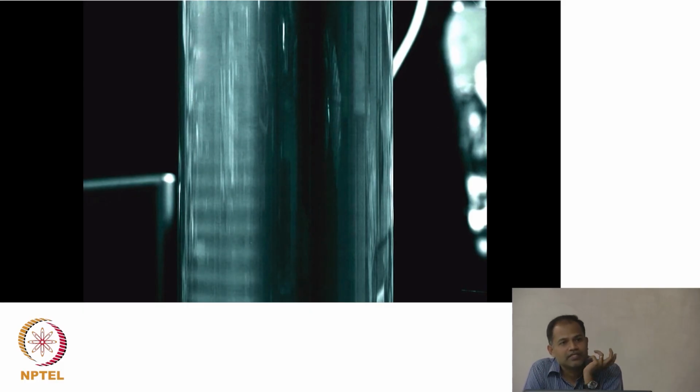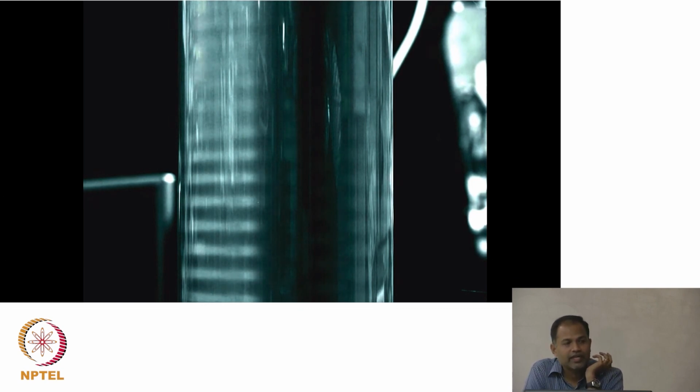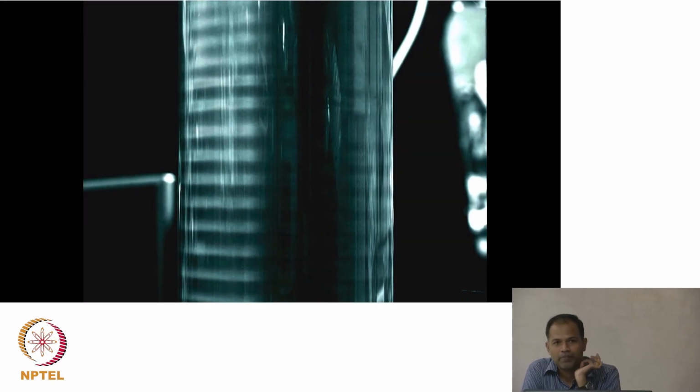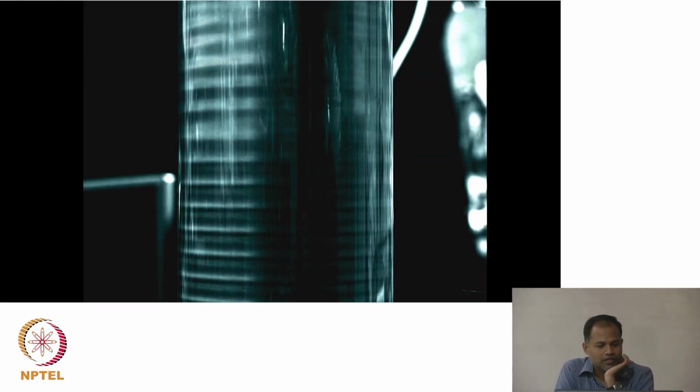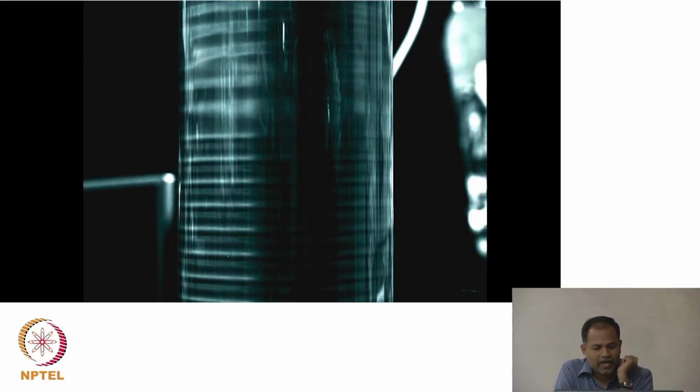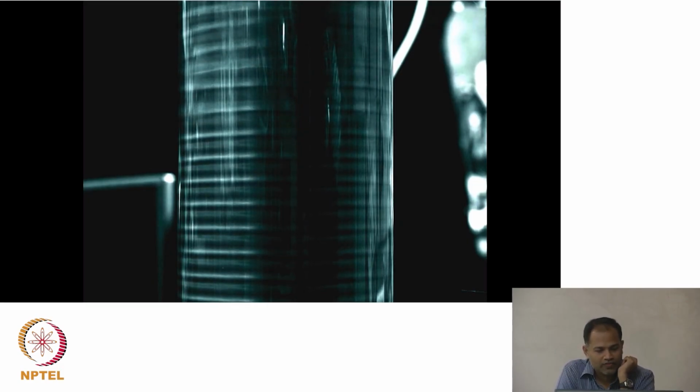Now, they will increase the speed of the rotating cylinder, which would mean that you are increasing the Reynolds number and the Taylor vortices start appearing. Okay. The square vortices that I talked about, they will look like bands. That is what you are seeing now. Okay. Now, with further increase in the Taylor number, these bands will become unstable and it will start generating waves.